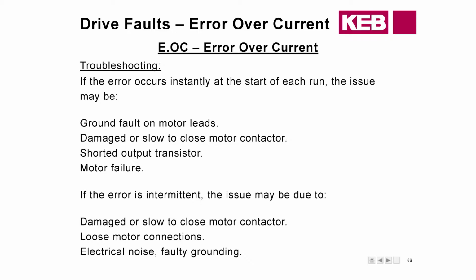The quickest way to figure that out is going to be disconnecting the motor leads from the motor contactor and then trying to run. If you don't get the E.OC after you disconnect the motor leads from the contactor, then it's something on the motor side to look at.